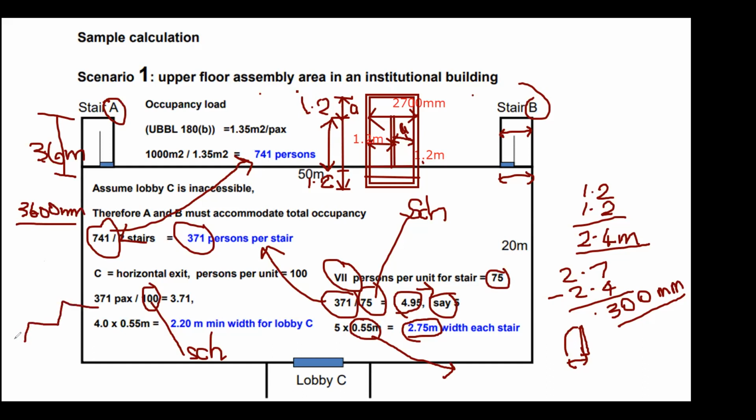See what is the minimum for the tread. This is the tread. This is the riser. How many? Minimum 255 until 280 mm for the tread. Do you know which one is the tread? The part you step on is the tread here. And this is the riser, not the riser for services, no. This is also what we call the riser. It's about minimum 16.